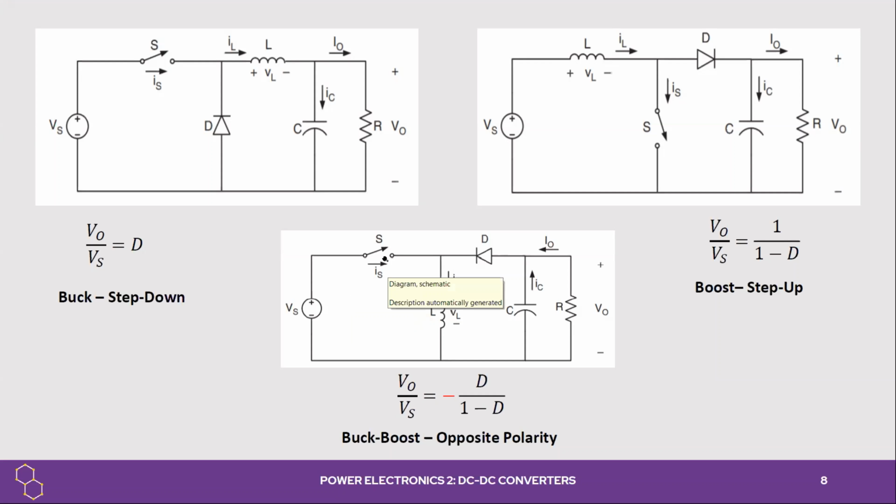So instead of that, you can think about it as a small manual switch, which goes on and off, so you can do an easier circuit analysis. Like when this is on, how you can do the circuit analysis, and when this is off, the circuit would be like this. You would remove this. It's easier to understand and to visualize. And in the boost step-up converter, you can see this is the transfer function, and the V output will always be more than the voltage source.